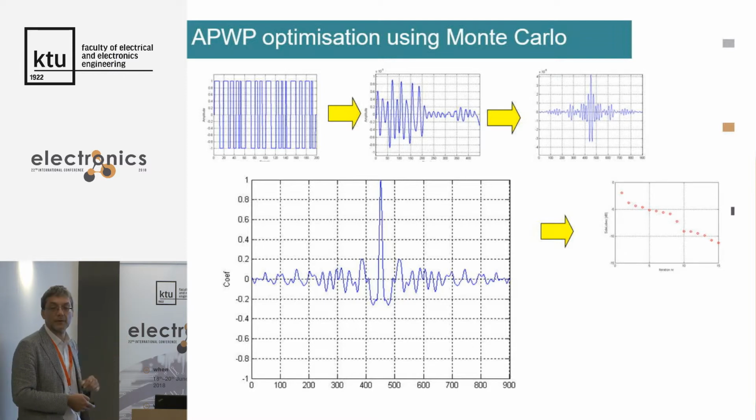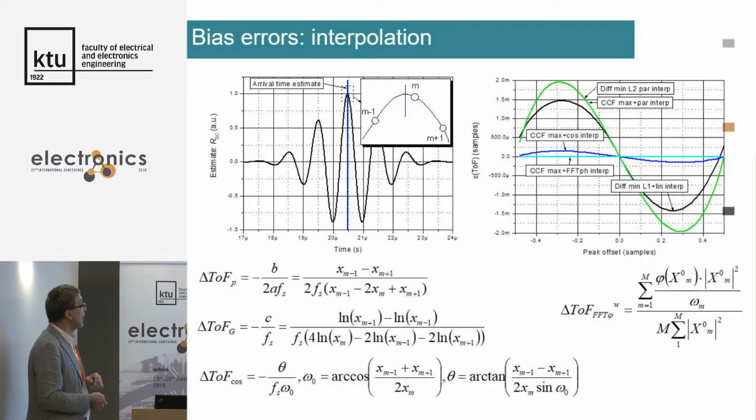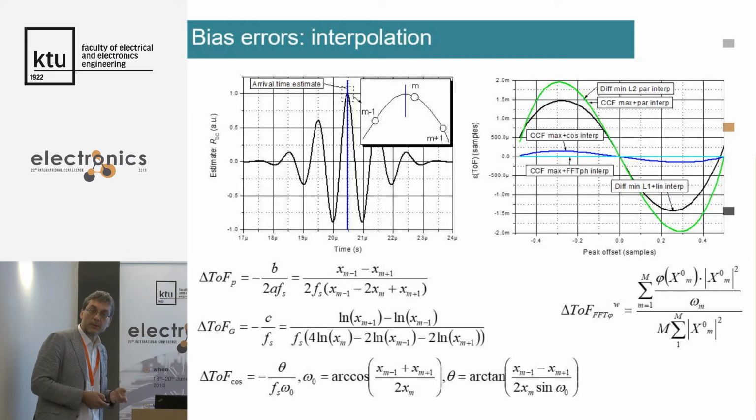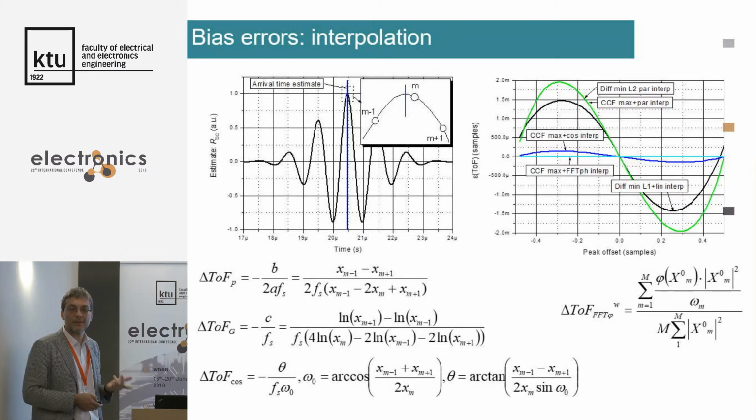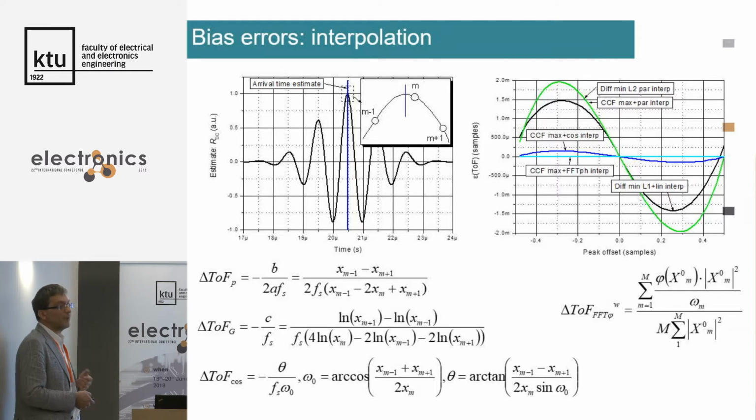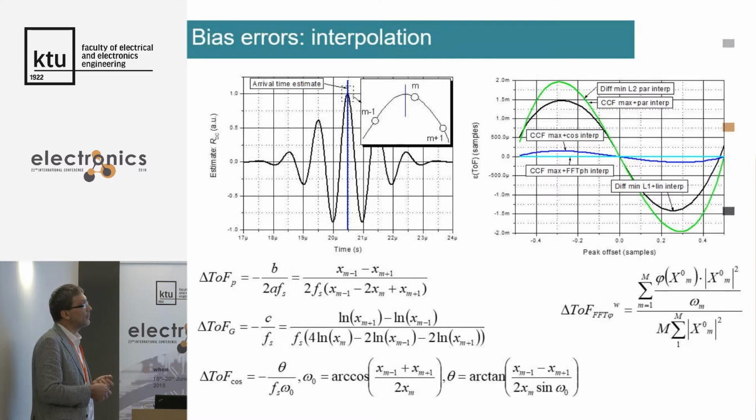And then, of course, we are avoiding the Barankin or Ziv-Zakai regions, because those regions come earlier if there are side lobes. Then when it comes to bias errors, because the previous discussion was on random errors, one of the sources is interpolation, because the ideal function for interpolation would be the sinc function. But usually in industrial equipment nobody has time, so they want to do it as simply as possible. So usually the interpolation is done over those points that are at the maximum.